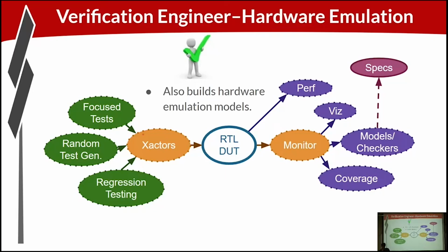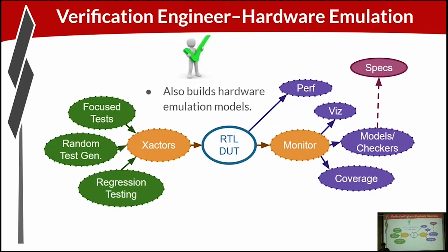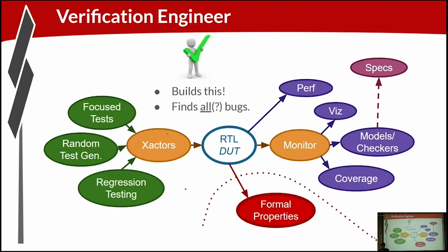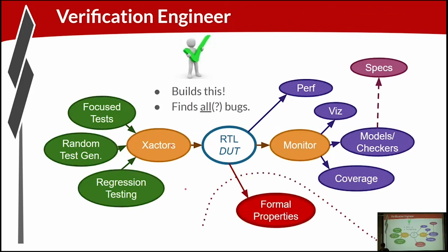But especially since the simulation-based environments generally come together sooner, the hardware emulation often, although it shouldn't be, often is an afterthought. Often these components get developed in a way that's not friendly to emulation. So there may be some additional work to develop transactors that are appropriate in this environment. You can afford to do a lot more with the transactors and the monitor in simulation, since your simulation speed is limited by the simulation of the RTL anyway.